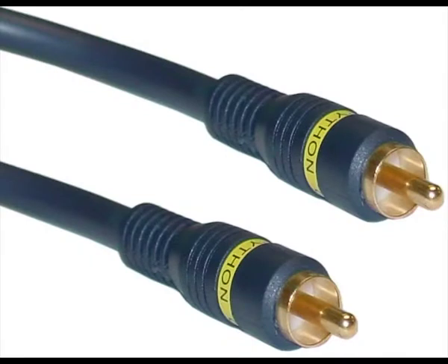The least separation and thus the lowest quality for a video signal is composite. When all the signals are mixed together and carried on a single cable as a composite of all the 3 color channels and the sync signal, the composite signal yields less precise color definition, which cannot be manipulated or color corrected as much as S-video or component signals.